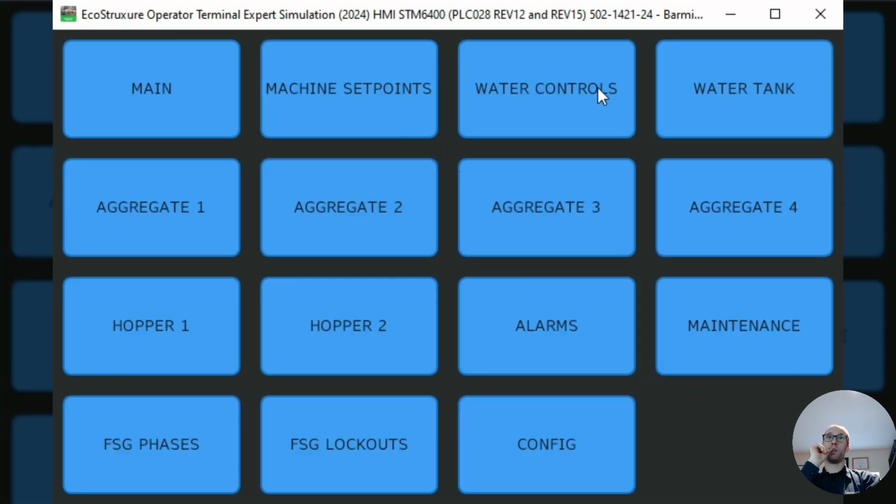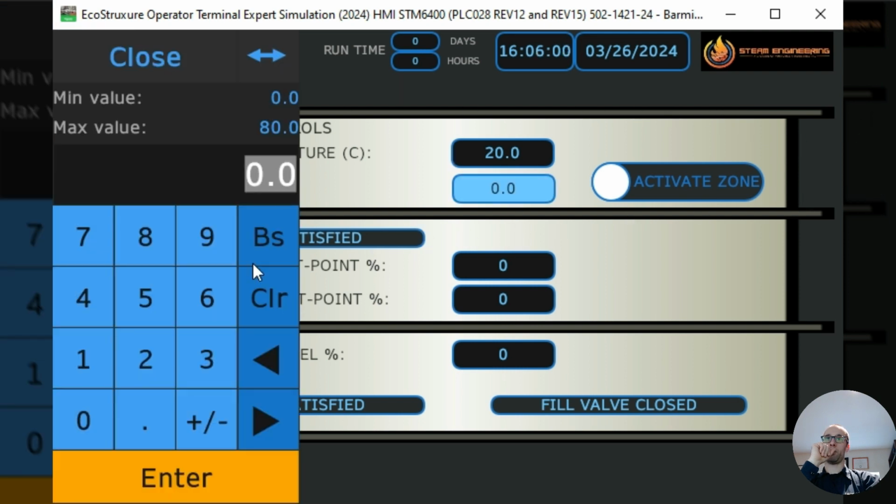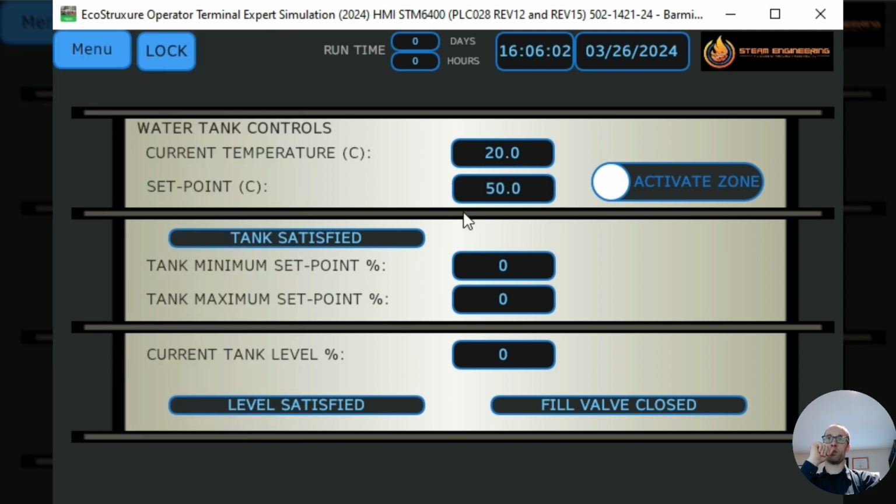We also have several other interface measures on it. So the water tank, if you are hooking up a water tank and wanted to do thermostating, you could set a temperature on the screen for whatever temperature of water that you want to maintain. It will measure the current temperature and it will be monitored on a simple on-off thermostat. So if this temperature reaches your set point, it will heat it up to the threshold, and then it will allow it to drop a 3 degrees differential deadband, and then it will resume heat to that zone again.